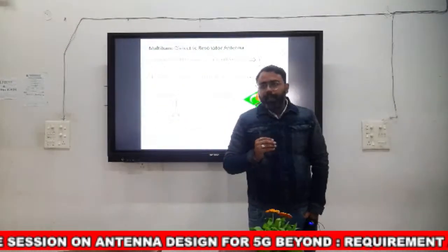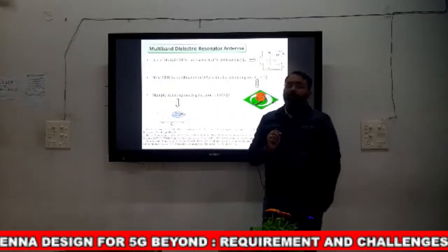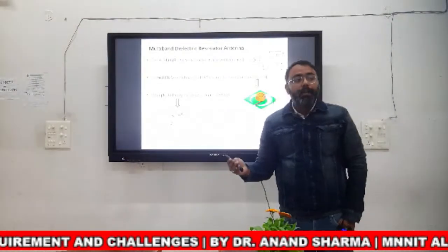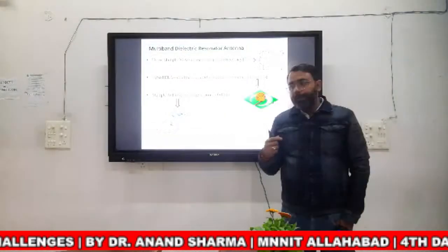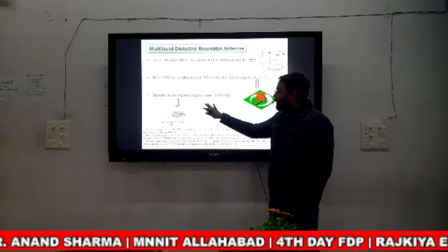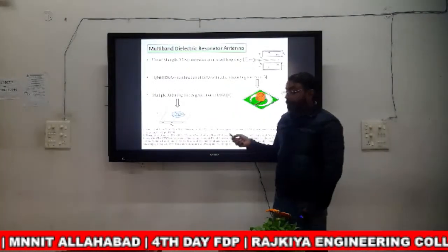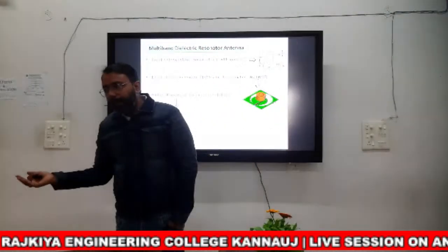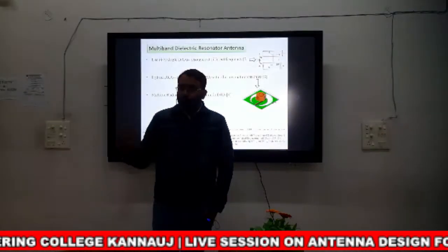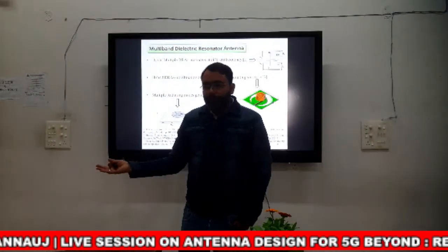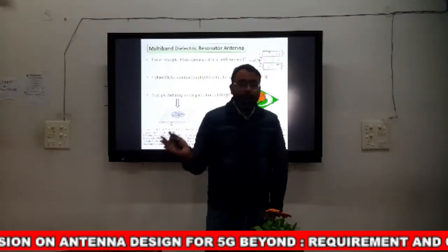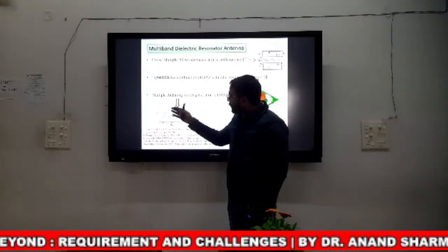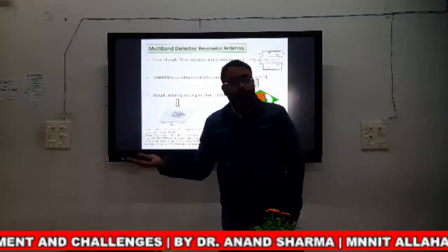Another thing is that you can also create multiple radiating modes inside the DRA to create multiband characteristics. It is a very important technique, and it is not very easy to generate multiple modes inside a single ceramic material. Okay, but it is an efficient technique because each mode, let us suppose I have 2 different modes, one is TM01, another one is TM02, each having a different resonant frequency, because each mode has its own cutoff frequency. So each has a different frequency, and multiple resonating peaks are created. Okay.